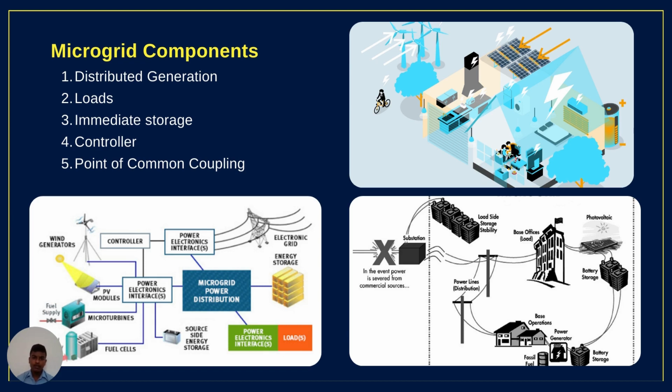So, microgrid components. What are the components of the microgrid? The components of a microgrid include controllable generation like natural gas, fuel combined heat and power CHP, and fuel cells; limited or non-controllable generation like photovoltaic solar array or wind turbine; backup generators, uninterruptible power supply UPS, and energy storage capabilities. The microgrid management balances the generation and load. The microgrid interacts with the local distribution network or the main grid at the point of common coupling. Let's move on, next slide.